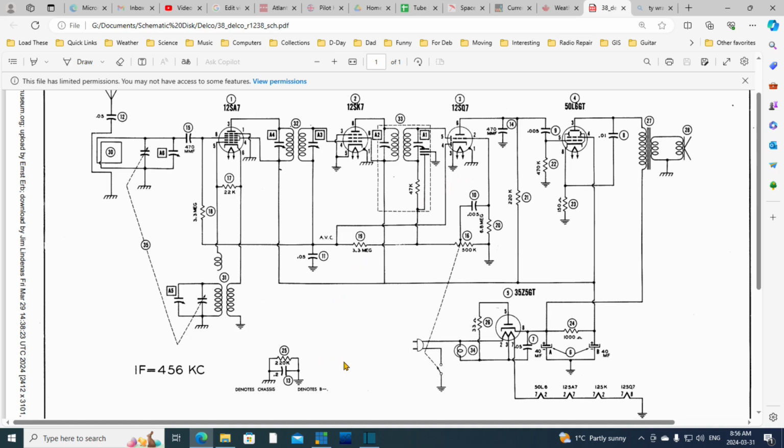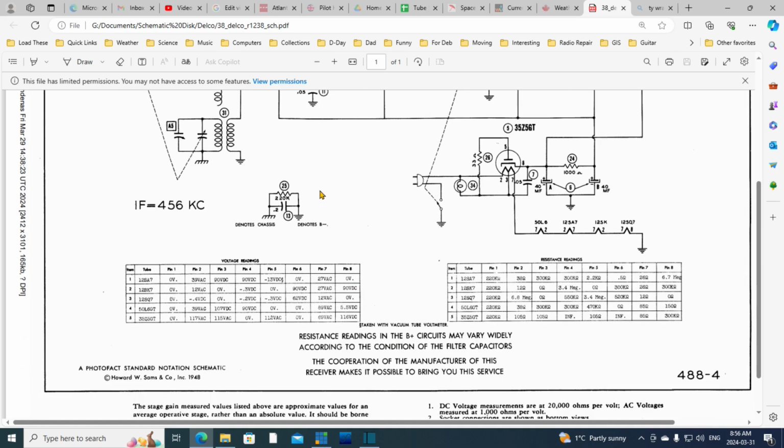Here's the thing I'm looking for, crying out loud. Yeah, I'm looking all over the place for this. So you see, here is a capacitor with a resistor in parallel with it. Oh, we didn't see the resistor just yet. This is quite common, how this is done. So, point to a very large capacitor. Chances are it's leaky a little bit, and a leak here could be dangerous.